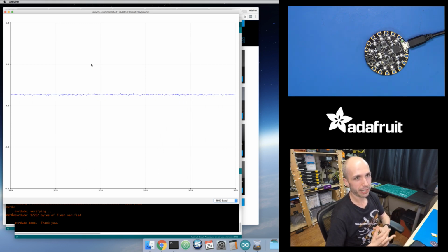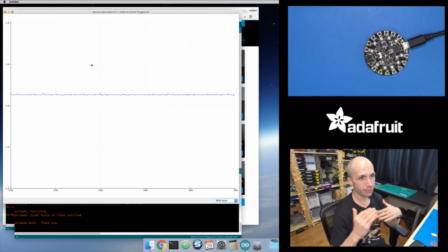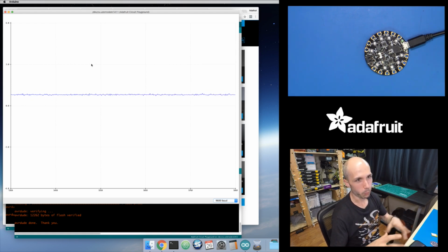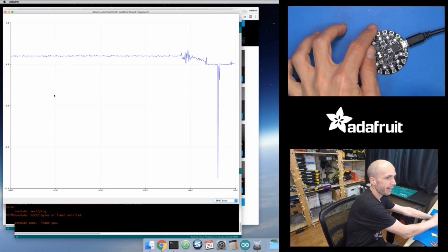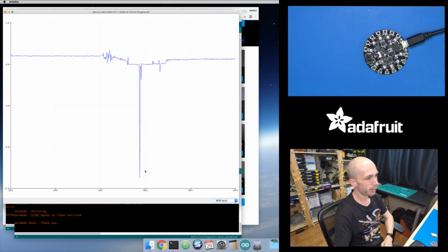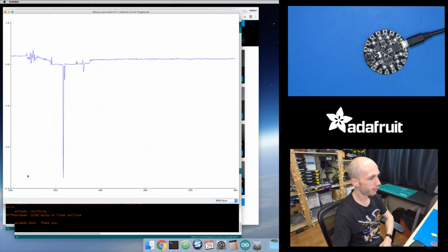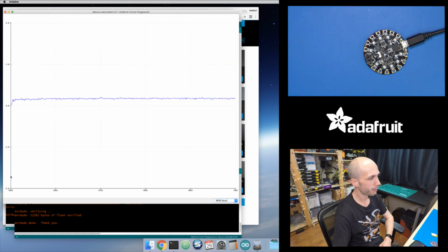The naive approach is you just set a maximum value, like a window that you're looking for peaks. You can see when the board is held like this, all the values are pretty stable, but if I smack it like that, I get this big spike, and so I get a big acceleration down to roughly -9 or so in one direction.